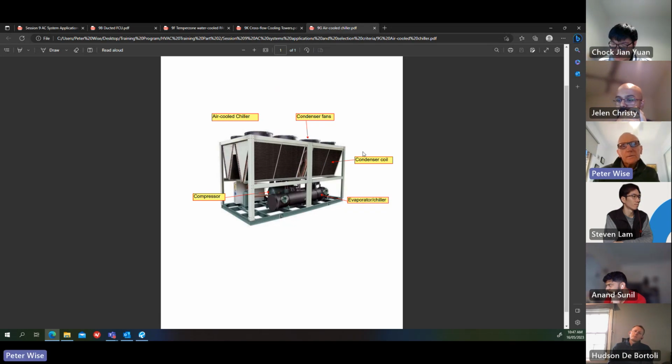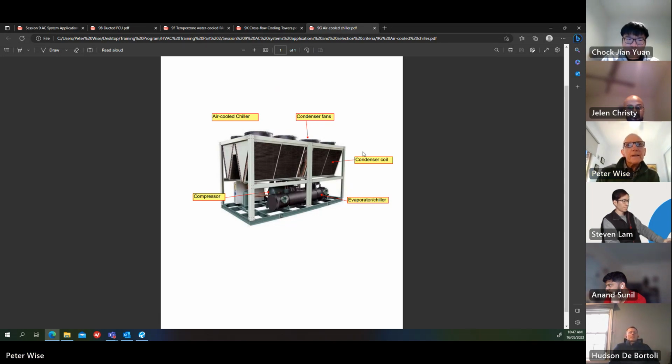If they want to build a wall around the chiller, you can do it, but you need certain clearances, and the clearances may or may not be in the chiller manufacturer's technical literature. If they're not, you need to talk to the suppliers and tell them what the architect wants to do, and get their advice on what clearances you need.